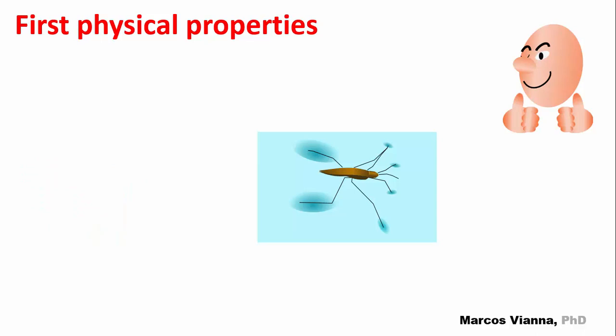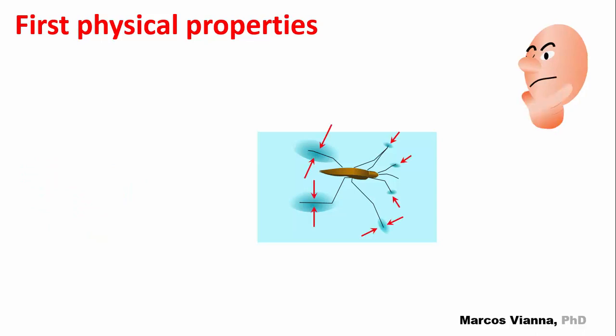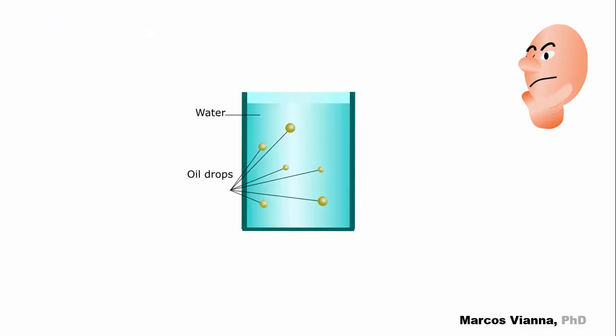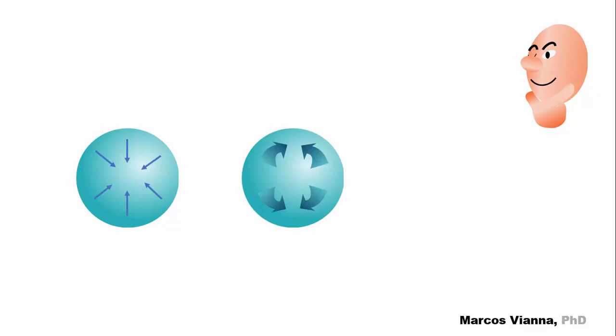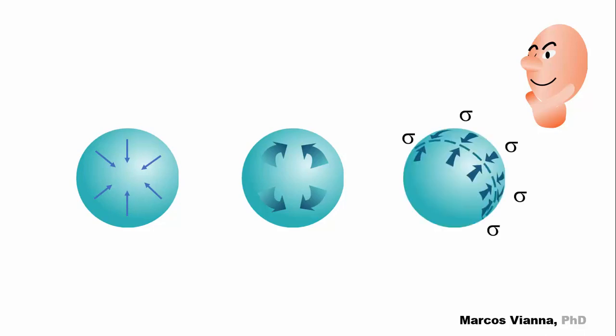What is it exactly? Well, we can say that it's a tension which develops on the interface of a liquid and a gas, or even between two liquids, caused by the intermolecular cohesion forces. In this way, the external surface of the liquid in contact with the gas, or with the liquid with greater surface tension, in the case of immiscible liquids, tends to contract. Surface tension is represented by a force sigma, which acts by length unit of the interface.